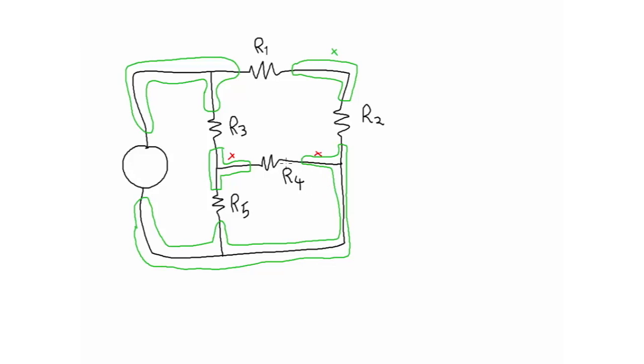For recognizing parallel components, it's possible if you can draw a line in a box. So you have a closed loop, and that closed loop goes through two and only two branches, then those two branches must be in parallel. You can probably see geometrically that's the same thing as saying that these two branches connect between the same pair of nodes. They form a little box.